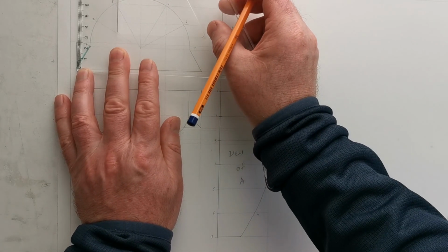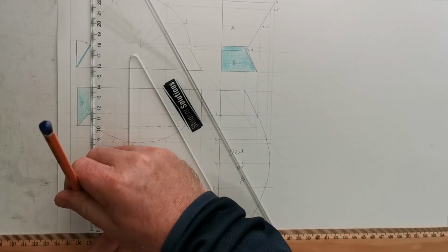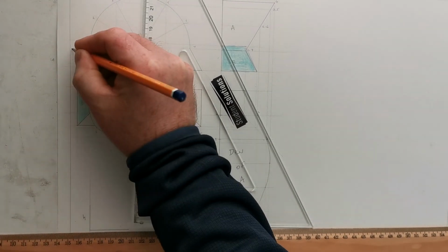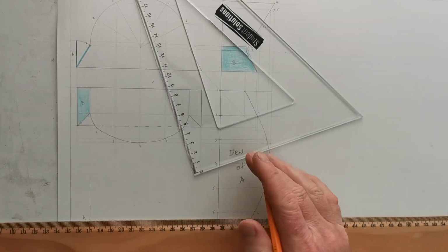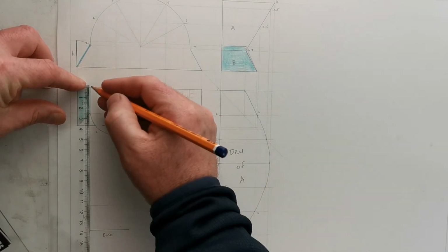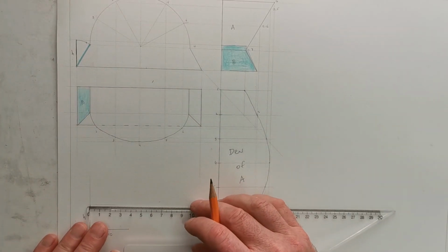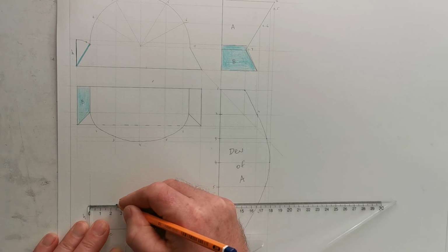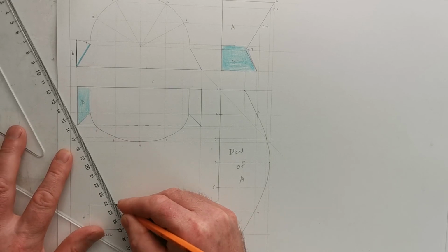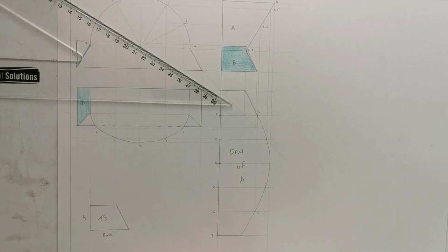So when it's standing up straight, it's 25 high. So I'm just going to measure 25 high. Okay, so that's my height. And the top of it then I can also get from here, because that's horizontal here. This is a true measurement. That's 25 as well in this direction. And that there is the true shape. I'll just put TS for true shape on that.